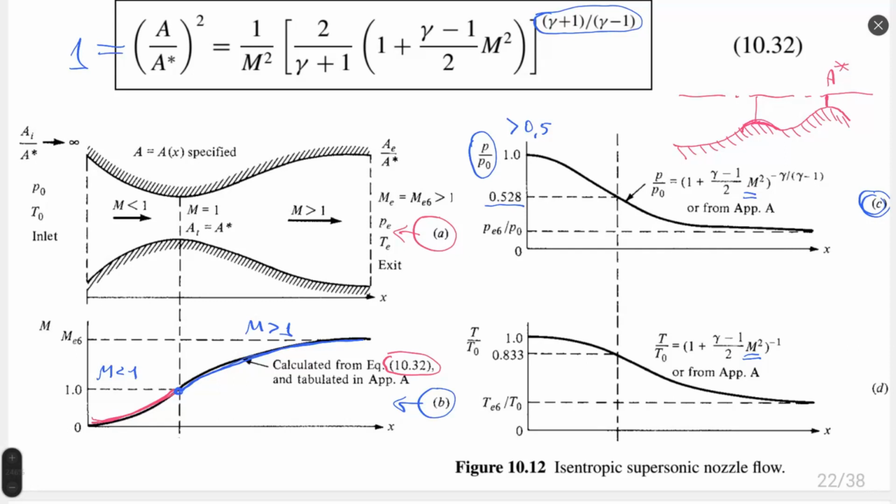So you have the relation between stagnation pressure and static pressure calculated. If you have something different in range in the subsonic section, you can consider it a wrong calculation. And in the supersonic section, we have a pressure ratio always smaller than 0.528. You can receive this 0.528 if you put Mach 1 in the isentropic relation, and you will obtain this value.